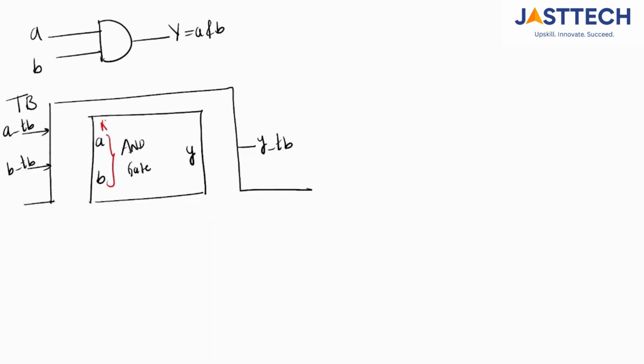They should be net data type. Input for this test bench can be reg data type or net data type, and output for the design is net data type or reg data type, and output for this test bench should be net data type.